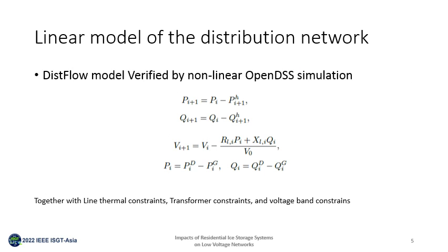So the models that we have used, there are three of them. The first one is the model for the distribution network. Here we use the DistFlow model. This model was verified by a nonlinear model simulation in OpenDSS. The equations are presented on the slides.